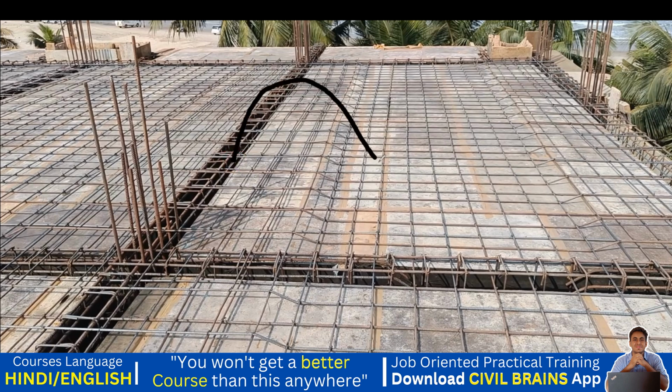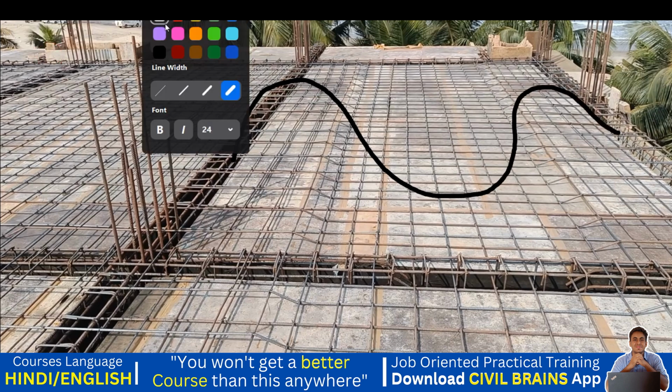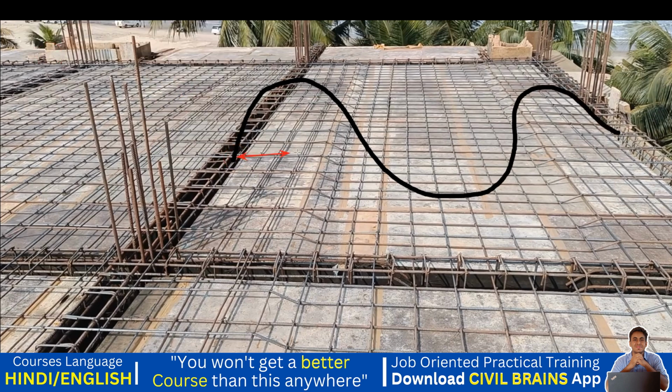What happens from here, it is sagging, again from here negative, right? So whatever negative is happening, let me quickly draw that. From here to here this is negative bending moment, from here to here whatever is negative bending moment. So till what point is this negative bending moment? According to the code book it says up to L by 4, whatever your span is, you divide it by 4, up to that the effect of negative bending moment will be there, and after that it is a positive bending moment. Got it? So that is why we try to give the crank bar up to a length of L by 4.